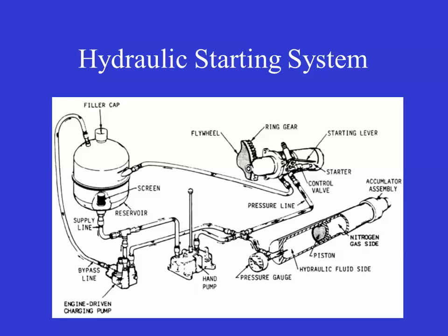Specifically, if you are working with one of these systems and you accidentally release a component that's under that kind of pressure, it will come out at an extremely high velocity and speed, and typically someone gets hurt. So you do need to respect these systems. But over on the right hand side, you can see that you have an accumulator that's going to be pumped up with high pressure fluid.